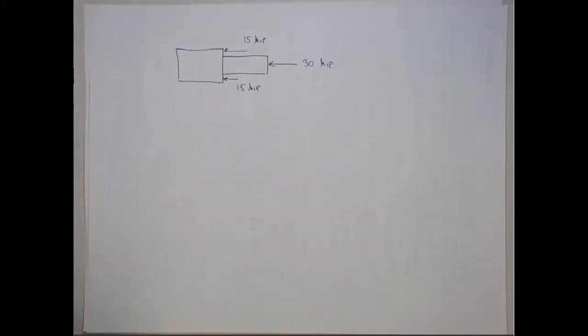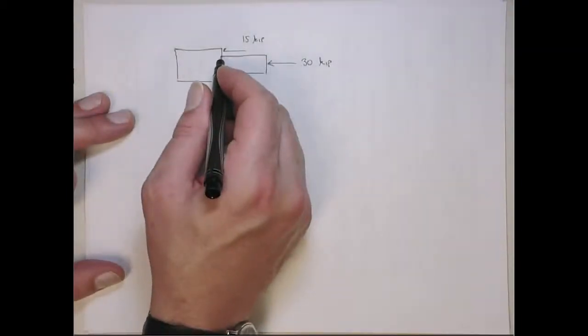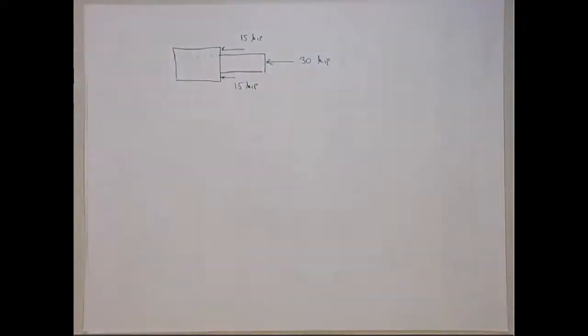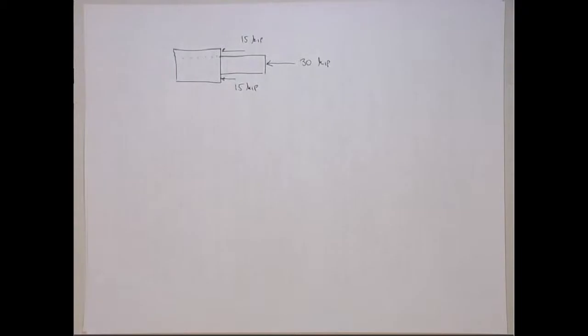In this one, let me just mention something. Some of you might be tempted to look at the shear along this line, and you could use the cross-sectional area. The problem is they don't give you the length. You would have to know this length to determine the shear across this area. Also, they haven't really given you the yield shear stress. It's kind of the reason why I don't like some of these problems. Kind of set you up. If you left it a little more abstract, you could go through that thought process. But it's a bit of a cop-out, but in this case, we're going to ignore shear because the problem hasn't been set up to do the shear.